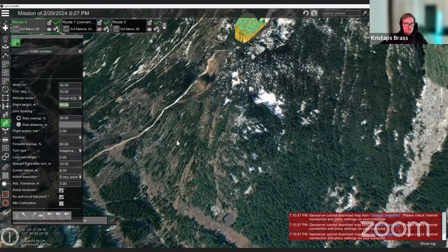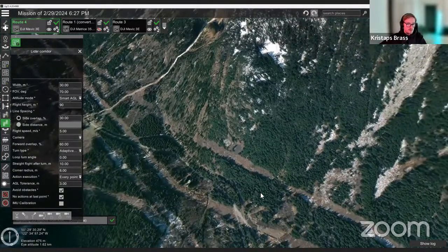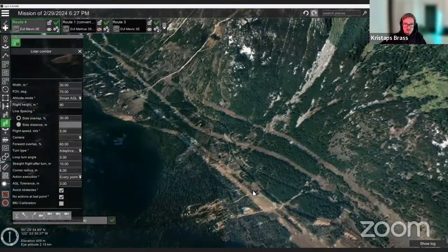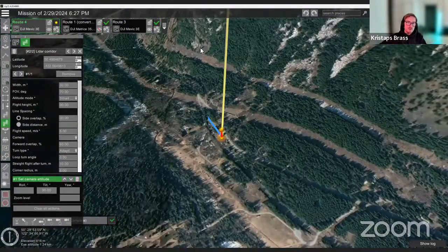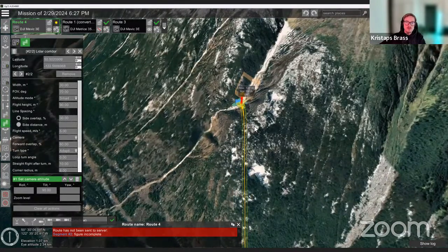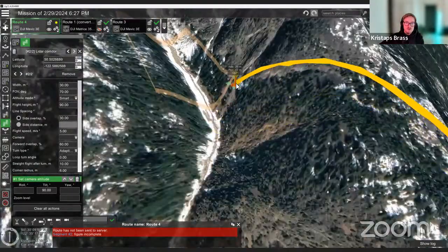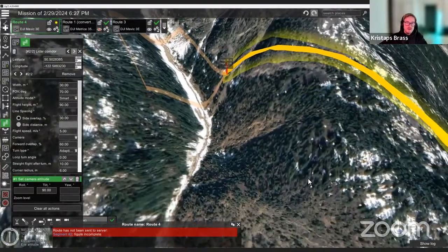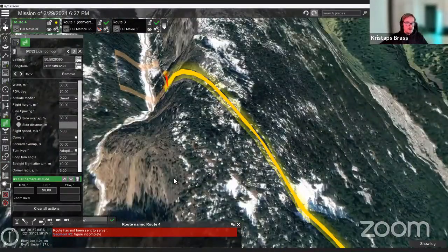So let's say I want to fly here at 50-meter altitude, maybe even just to be safe, let's do a bit higher. So width is 30 meters, and then let's choose where we have parked our car, let's say over here. So we can then place one point over here, and then next point of the corridor, we can place, for example, somewhere over here already. So basically at the very beginning of where we have our photogrammetry mission, maybe even a bit closer to this corner.